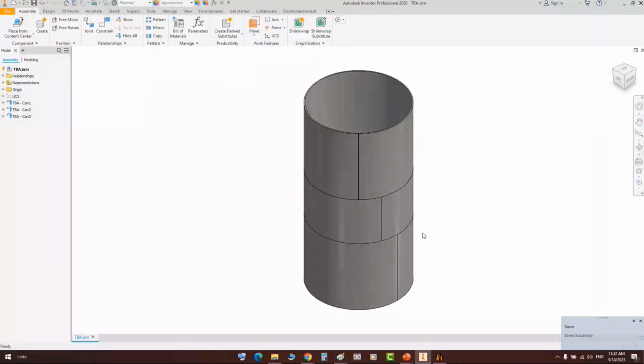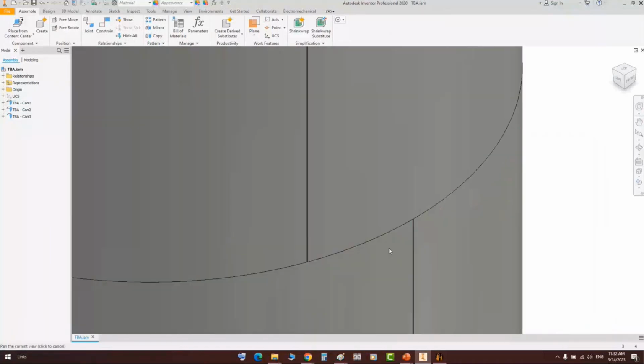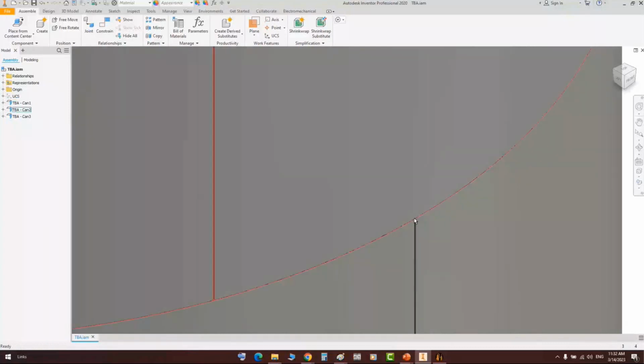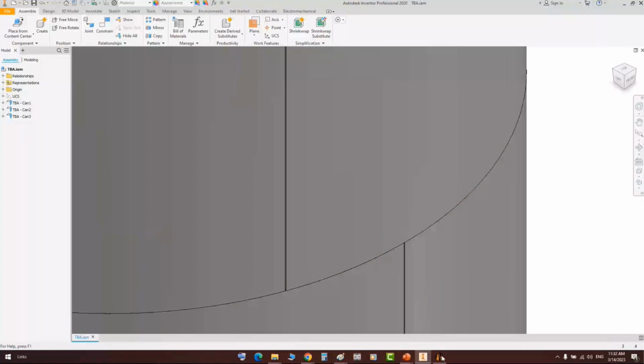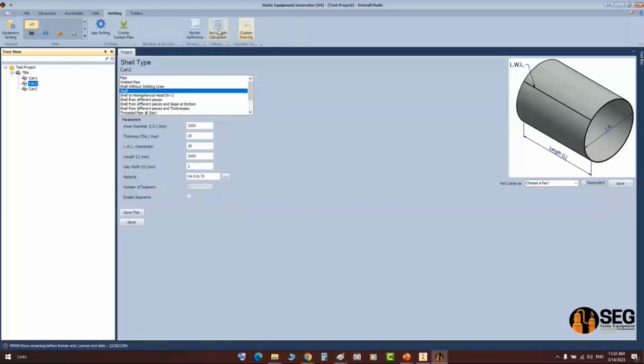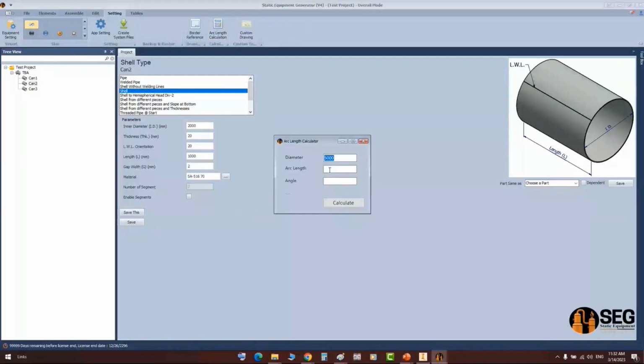Now, let's use another option, for storage tanks, if you would like to make an offset from here to there with a defined distance like 2 meters or 3 meters. By using this calculator here, you can do that. For example, here for this vessel, that's the neutral diameter, and from here, let's make this offset 3 meters, for example.